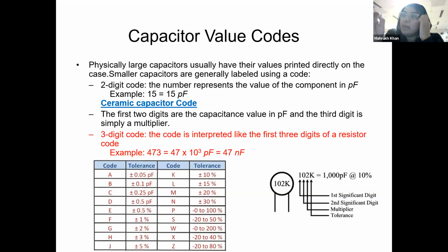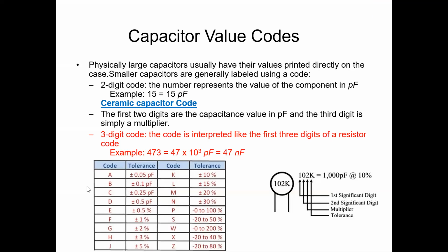Okay, so this 100 microfarad capacitor, if you look at the top of this capacitor, you can see three numbers, 107 and a capital M. It's very small, but you can read it. 107M, right? Can you read that? Do you have capacitors with you? Yeah, I'm just trying to get it out of the bag.